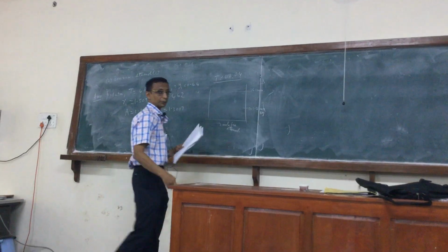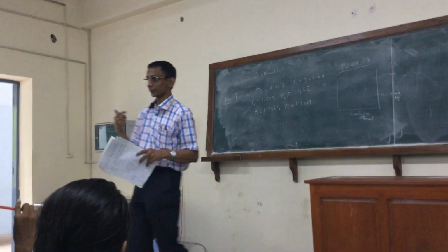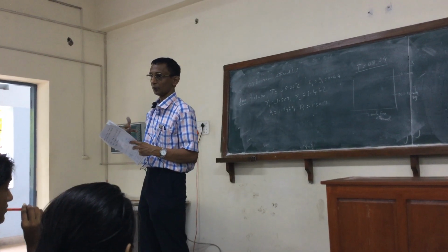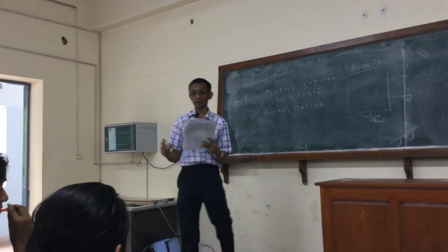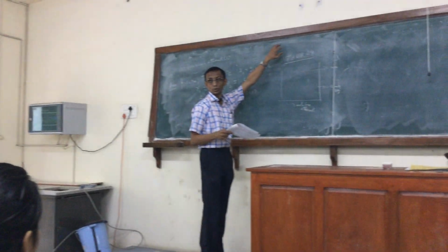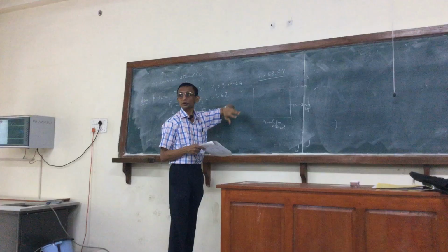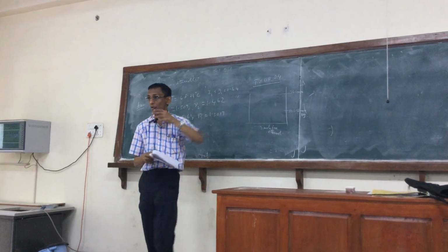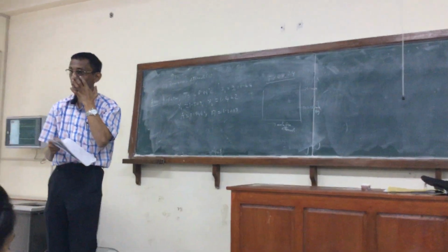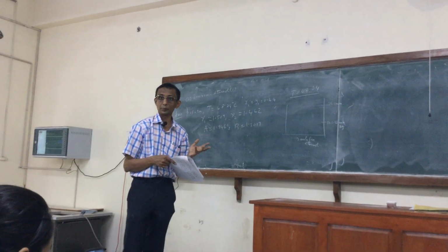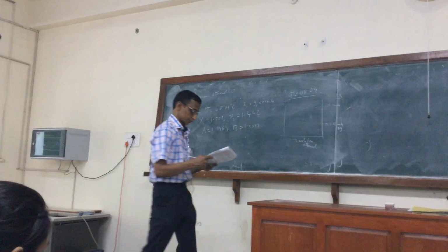So the argument that we made was if it exhibits a minimum boiling azeotrope, that means Pxy at constant temperature will have a maximum. We can correspondingly show that at the azeotropic temperature, Pxy will actually exhibit a maximum. If you know what minimum boiling means, you look at the Pxy diagram to conclude whether it is minimum or maximum.